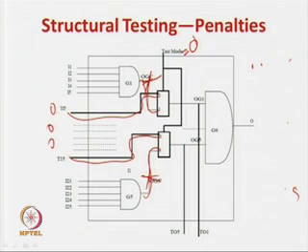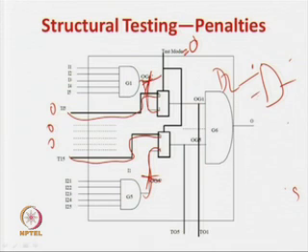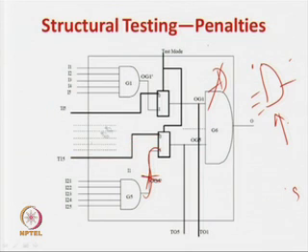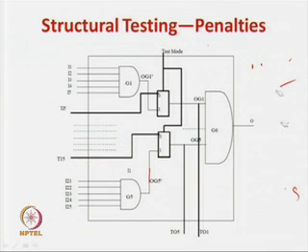Now see what we have done. This is the gate and this is the line. This is the internal gate, some other gate which is driving it. Now, to apply a test pattern, because our idea is to test this gate individually rather than the whole circuit, what we have to do? Some other gate is driving this gate. So in the test mode, somehow we have to make this gate unable to drive this, and there should be some extra pin outs which can now drive this gate, so that you can apply test patterns as you like and test this gate individually. This is possible in all cases by using a 2:1 multiplexer.